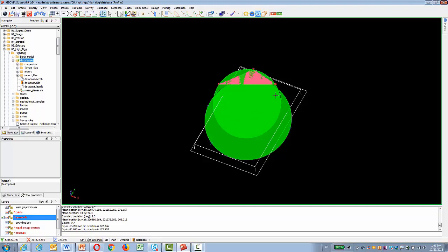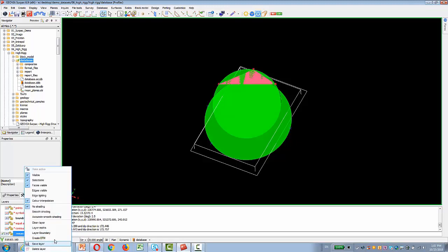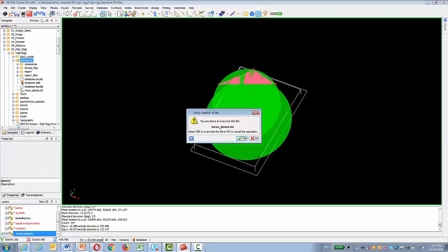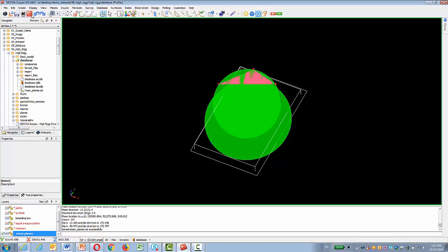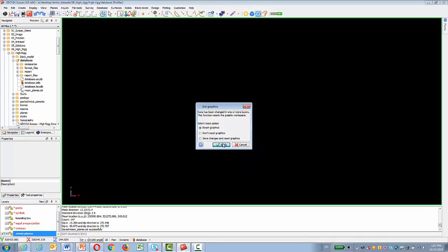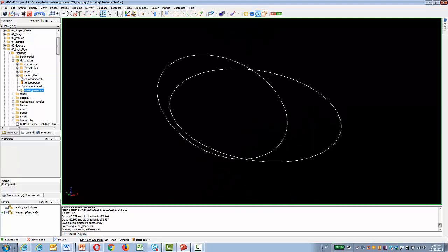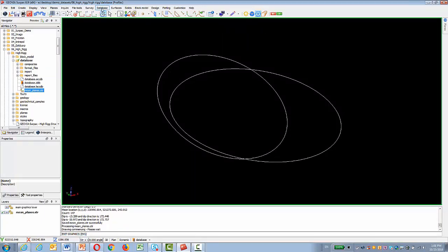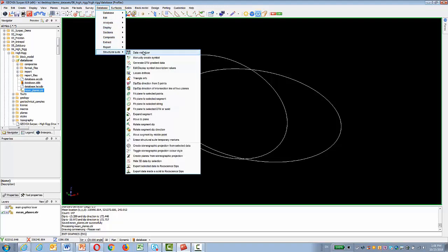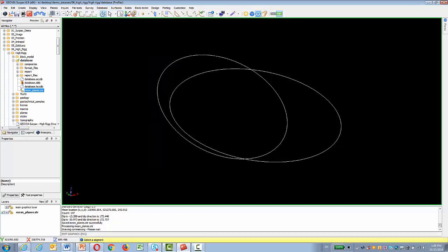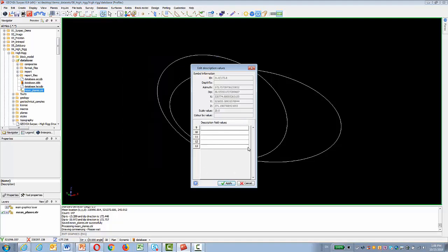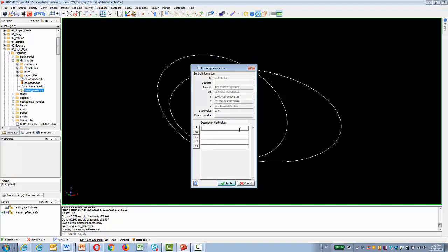Additionally, if I wish to save this information, which is very straightforward, I simply save this layer. Then I have the information available to me as a very simple string file, which I can then choose to format however I would like later on. And if I want to, I do have the ability to go in here and make changes to the data by adding some extra description fields. You'll notice that the azimuth and dip information is automatically stored with the symbol as well.